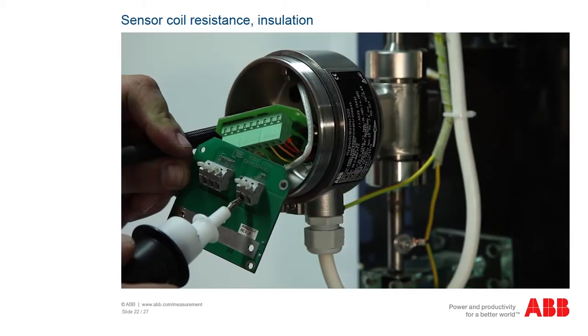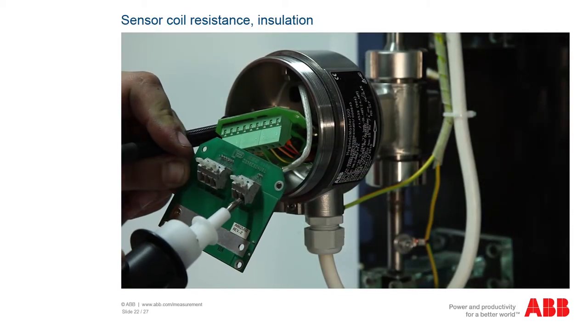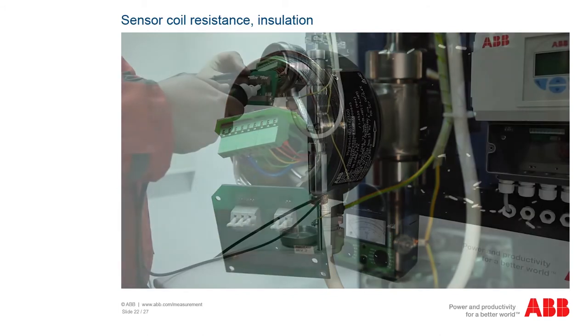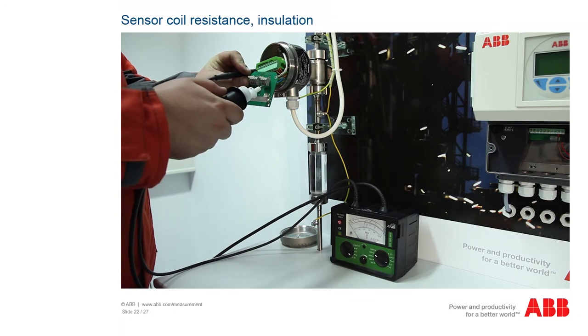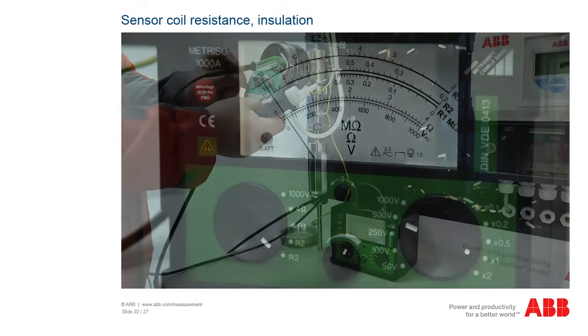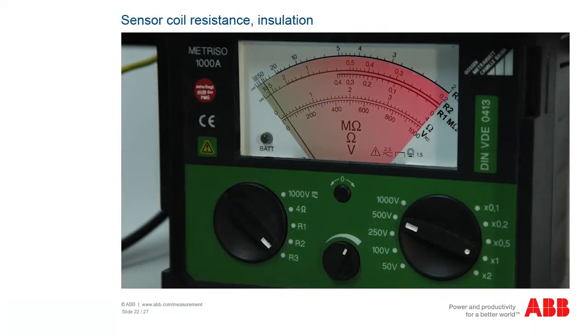Now measure the insulation resistance of the coil at contacts M1 and M2 of the smaller connector on the XE board. If the coil insulation is OK, the insulation measuring device display must not move at all. If movement is visible, this indicates a faulty coil insulation to earth. Enter the measured values in the measuring log.